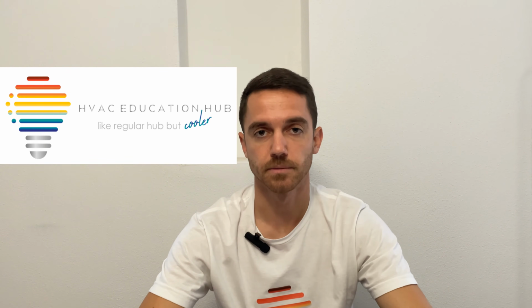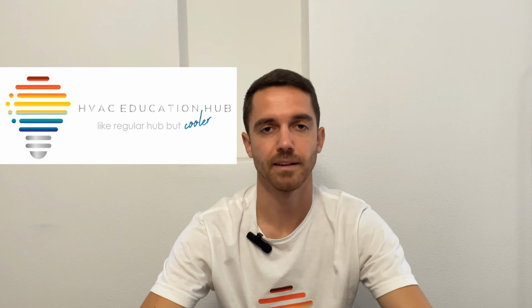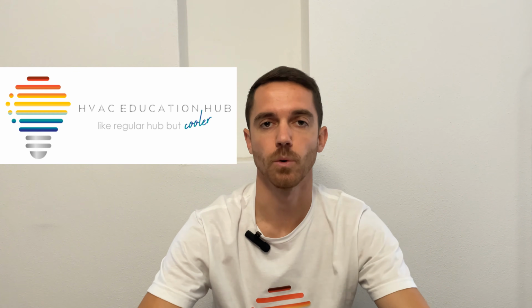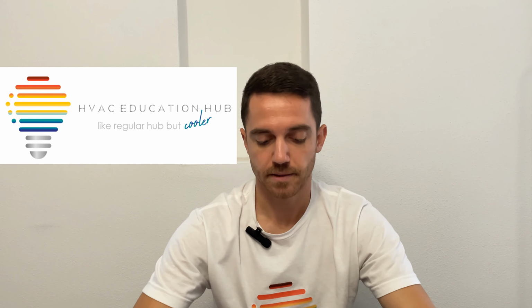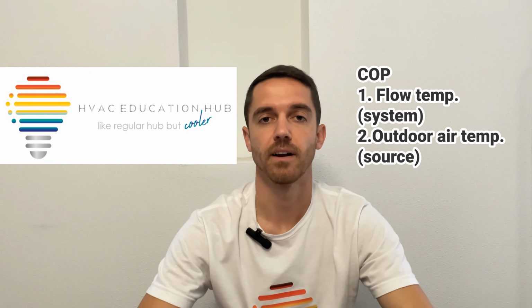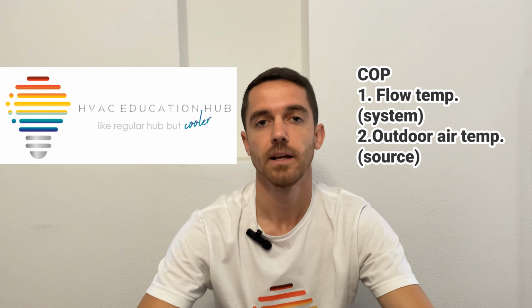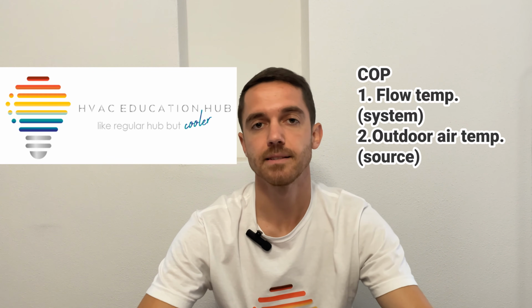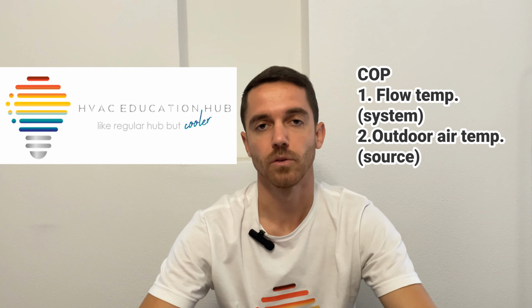There are also some other parts like pumps, fan motors, and sensors, but this is very low consumption, so we'll focus only on the compressor side. Regarding the thermodynamic formula of COP, we can see that there are two main variables: the temperature of the heating system and the temperature of the source. It means that it doesn't depend on insulation of the house, as a lot of people are saying.